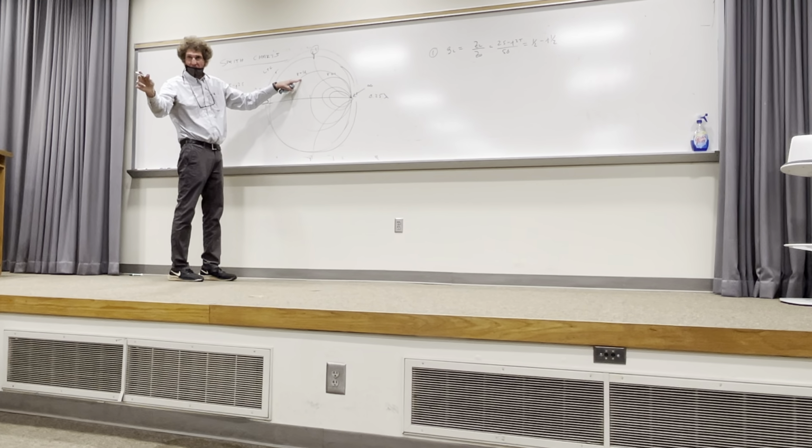Now, you're going to see something on the wavelengths towards generator marking, something in wavelengths here. It'll have wavelengths towards generator, blank wavelength. I call that a mile marker, like a highway mile marker. What do you read for there? What point is that? 0.412. All right, 0.412, that sounds about right, and I'll tell you why. 0.412 lambda. Go ahead and take a look. How many see that? Right, remember, it's wavelengths towards generator.